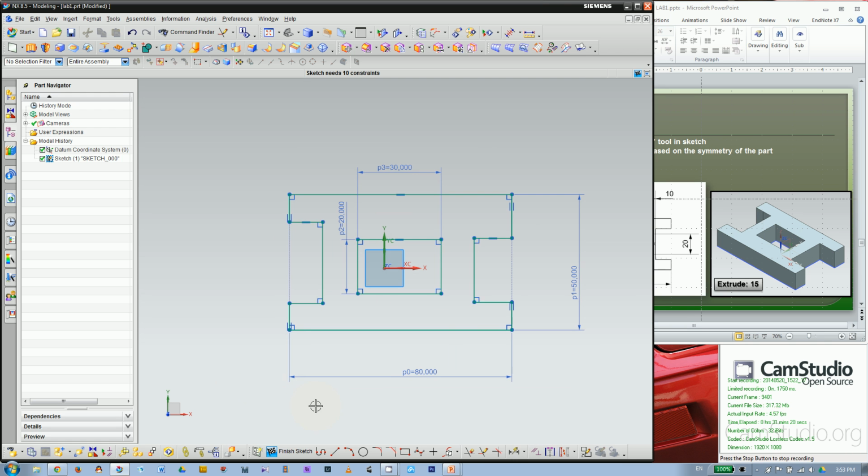Okay, so in conclusion, in sketch we introduced the profile, then rectangle tools, mirror curve, and quick trim, quick extend. Then you have inferred dimensions. You can convert your active line into reference lines. By the way, you can also convert your dimension to reference dimensions, which only tells you how long the line is. It will not drive the actual size of the lines.